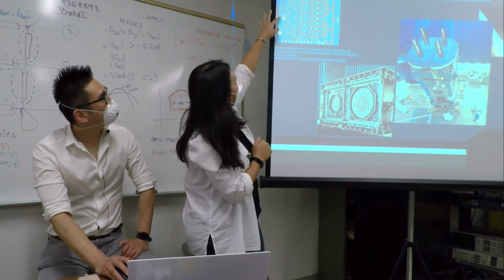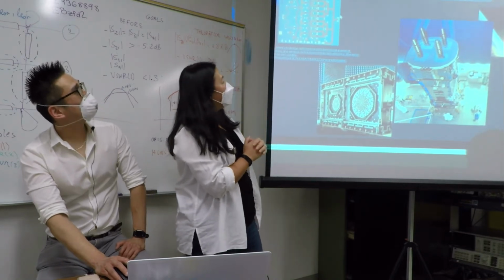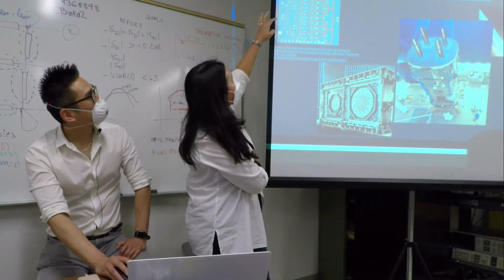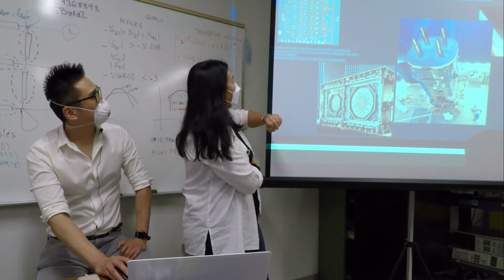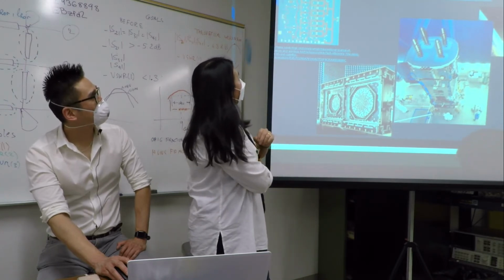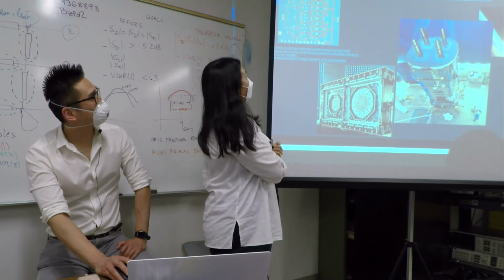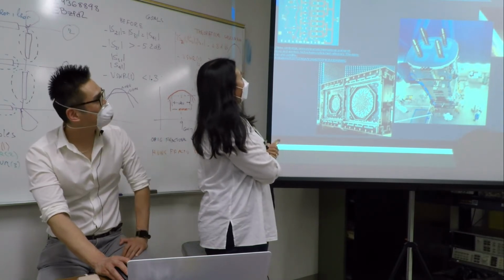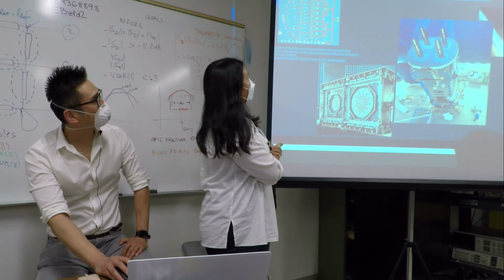This is the RF input here, and this is your RF out here. The input and output consist of a series of 3 pads. Typically it's ground, signal, ground. I said ground is important, right? This structure is done a certain way so that you carry the impedance from wherever the signal is coming from into the chip, so you still stay matched to 50 ohms, for example. Even the spacing, the size of the pad, the gap, the dimensions of the pad are done a specific way so that we keep a 50 ohm match.